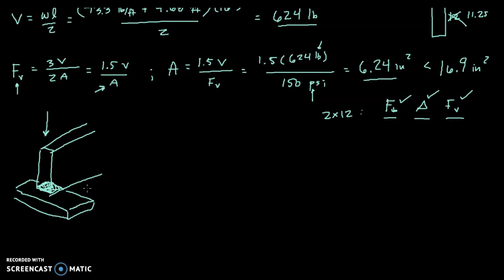The last remaining thing to check with a timber beam is the bearing area here. So at the end of a timber beam, it sits on top of something. And depending on how big this rectangular area is, it will affect the stress. And as we mentioned before, wood is very strong parallel to the grain, but relatively weak perpendicular to the grain.